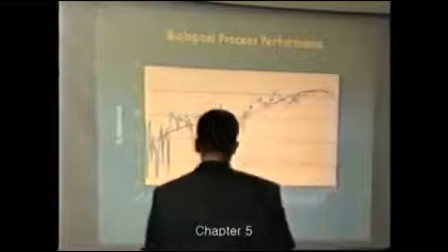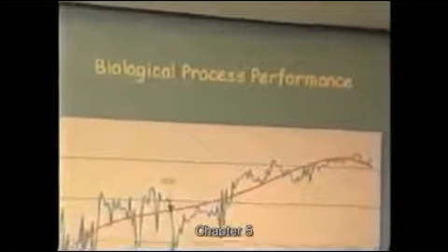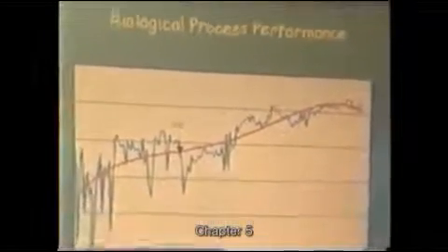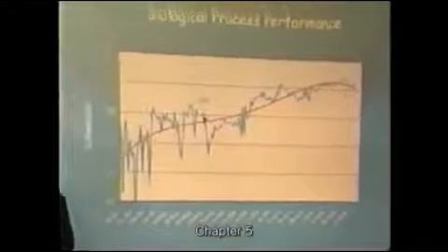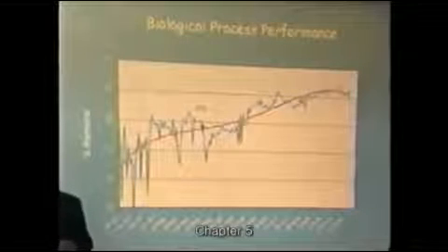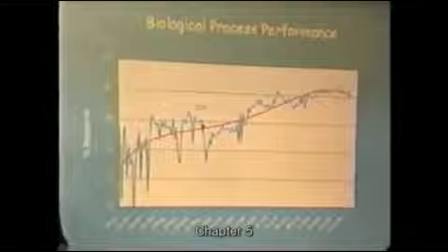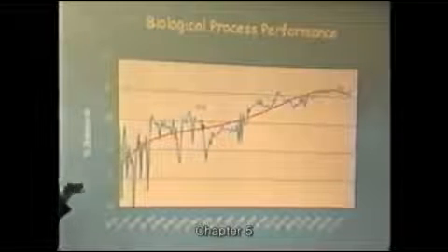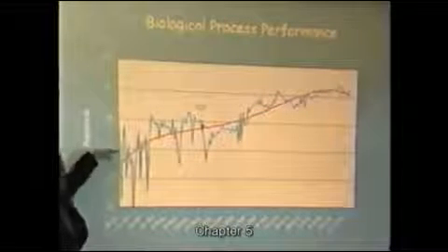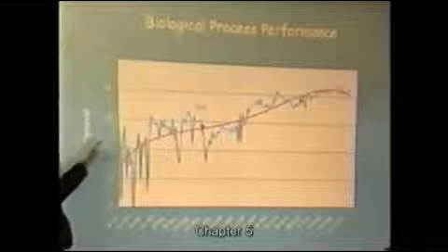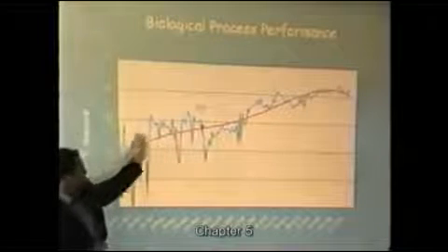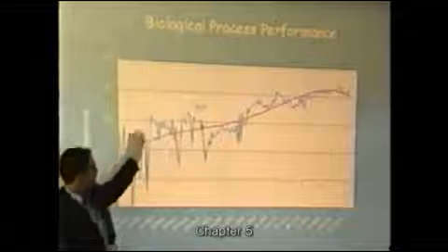This is the performance curve we got out of a little pilot plant we did with Sasol. Sasol is a big petrochemical company in South Africa, where they start off with a COD of approximately 20 to 30,000, and they had a typical performance of about 85 up to 90%. Interestingly enough, they added micronutrients before we started.